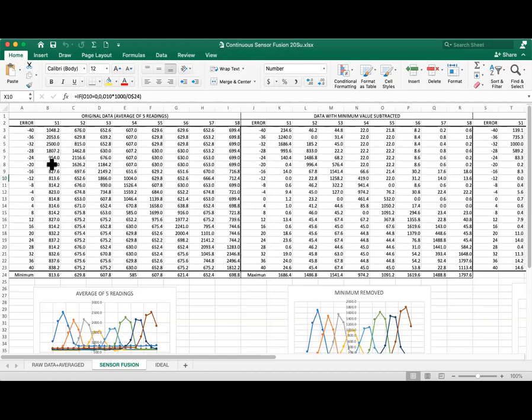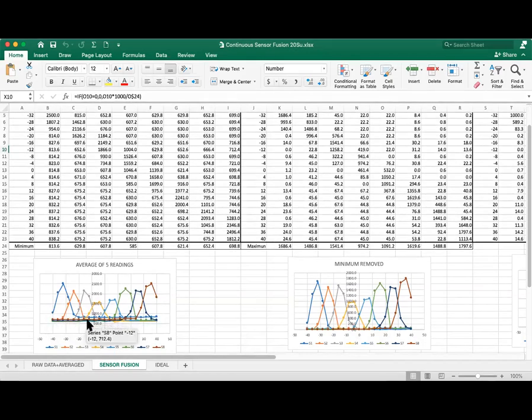So anyway, you can see that the numbers kind of get larger on a sort of diagonal as you move the thing across. And here is a plot of those numbers. And you can see now what I've talked about before. The center ones seem to have less gain for some reason than the outer ones, but it's okay, we'll fix that. And you can see also that, for instance, this leftmost sensor, when it's seeing only white, is at a higher reading than all the other sensors when they see white. So we've got to remove the zero offsets first, and then we've got to correct the gain offsets.